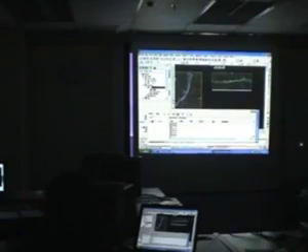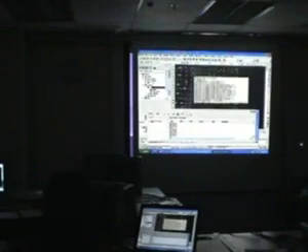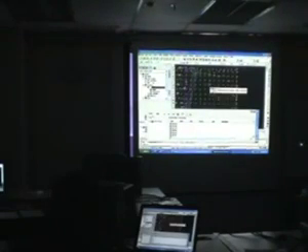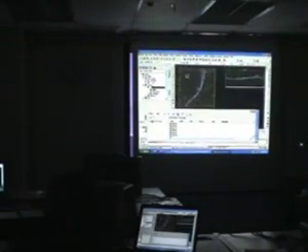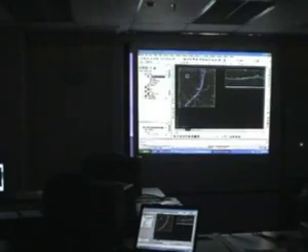The only thing here that has not been updated is the corridor. The corridor that I'm talking about is sort of like a 3D model of the road, because this model has to be generated. It's not directly connected to the horizontal and vertical, as you can see. But it's really very easy to update. It gives you a warning, hey, this is not updated. Just right click, rebuild.